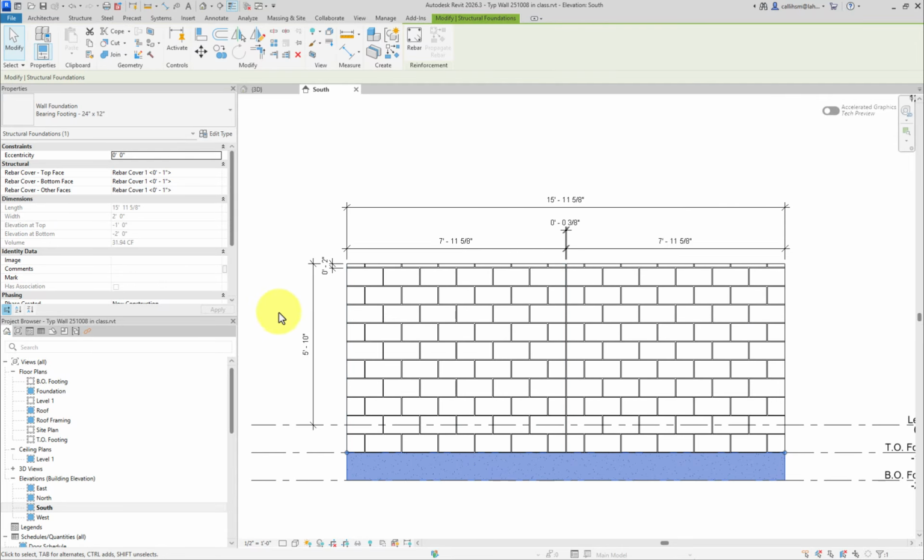We're doing it to make sure we understand three-dimensionally how all the small pieces fit together and how the rebar fits together. So right now we've got a control joint that's 3/8 of an inch here in the middle. Our total wall is 16 feet, but it's not really 16 feet because it would require another joint of cement out on the edge to reach the full 16 feet based on the concrete block module.